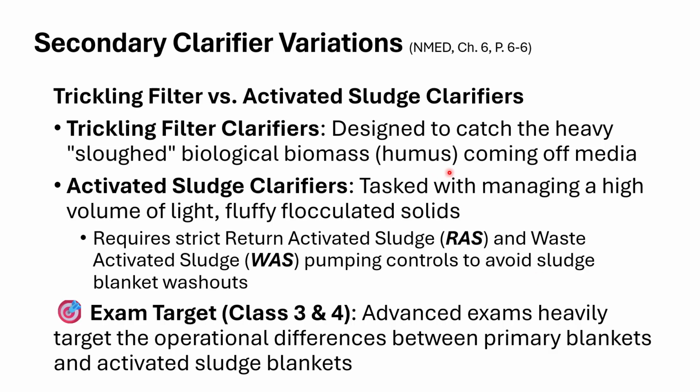And what I'm also going to tell you is those three metrics, I've got a separate lecture on those because it would have taken a couple hours of a lecture to get through those plus the sedimentation and flotation material. So I've got a separate lecture for those three items, the weir overflow rate, the surface loading rate, and the solids loading rate. I'll record that and it'll walk you through how to calculate those things, okay?